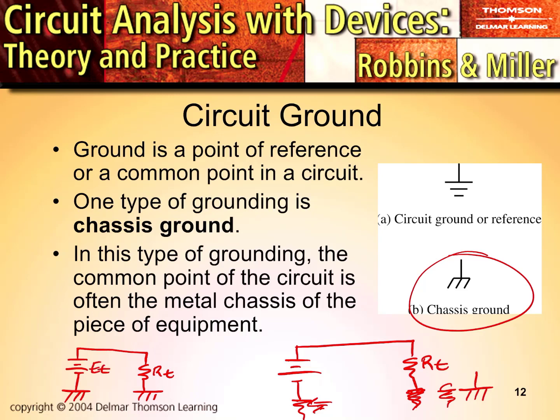How does the return path, or the closed loop, occur here for current to flow? Well, what it means is there's an actual connection made by the conductive chassis that allows this loop to be closed. So what do we have? We actually have a connection made by the conductive chassis that becomes a common point of reference.